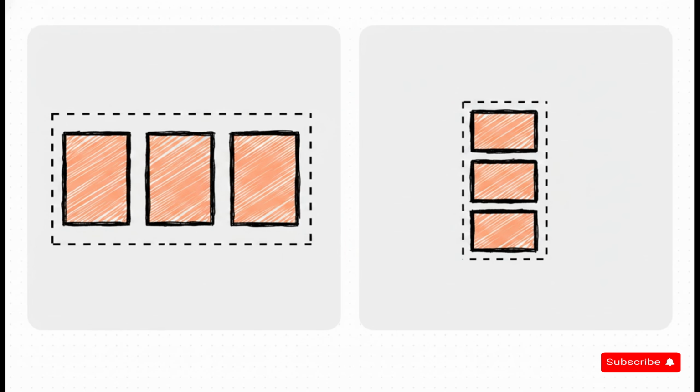You can adjust the width of the channel simply by changing the thickness of those nanosheets stacked on top of each other. What that means for designers is that you get a much higher drive current for the exact same footprint on the chip. It is basically the ultimate space-saving maneuver to mitigate those short channel effects, and it's exactly why GAA is taking the crown at the absolute cutting edge of manufacturing right now.